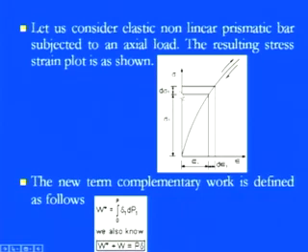Now if you are taking a simple element of this particular slope, meaning the nonlinear term, then with that consideration, if we take a small segment d sigma 1 and d epsilon 1 in the sigma epsilon curve. So you see here, after focusing on that part, we could simply check that under these particular regions the strain energy is there, and under these regions the complementary strain energy is there, and what you see the significance is there.